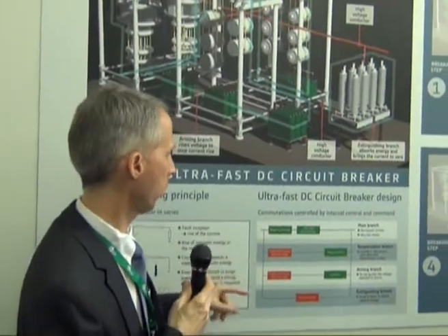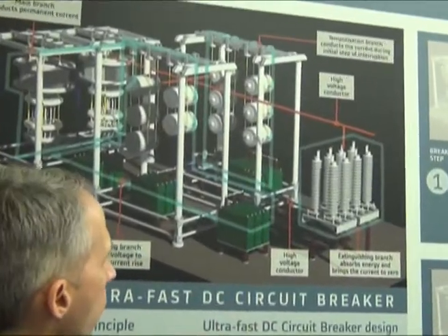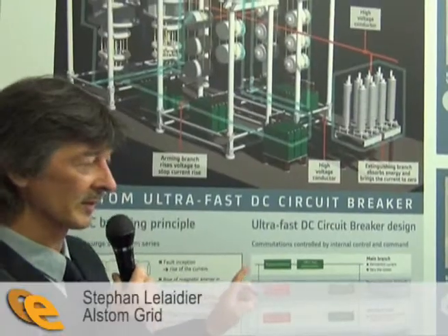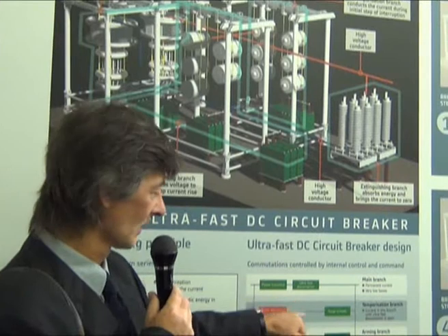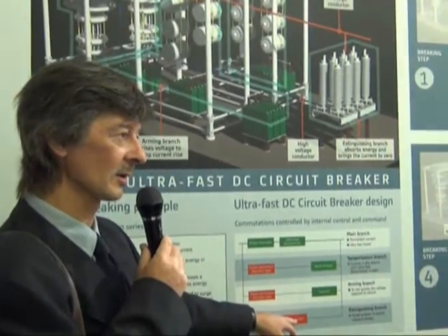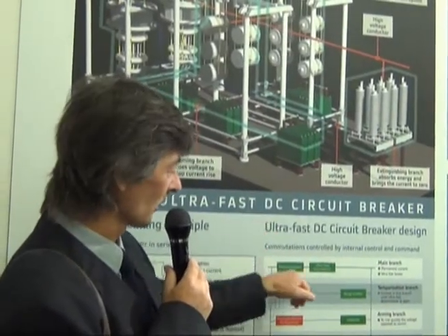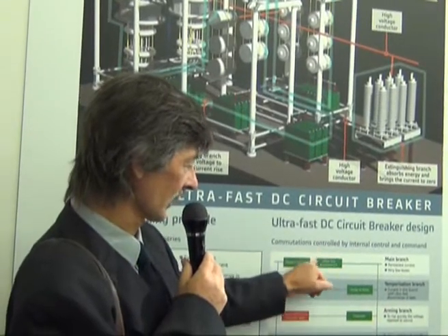If we go a bit more into details and put some real physical elements behind this, these are the following slides. Because in fact what is important is this element, which is a mechanical disconnector, and all these branches, in fact, they are used to wait for being able to go in this one with the surge arrestor in serving the network. And when the current is growing, we want to cut the connection, but this is mechanical, and it is not fast enough to sustain the voltage which could appear if we start to open.